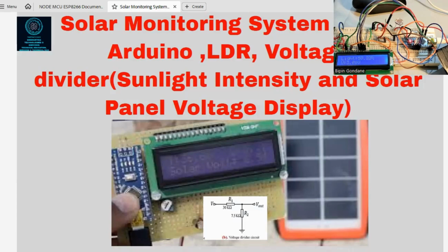What happens is that the sunlight intensity is measured in lux and displayed on the display. You can see on the top it is displayed, as well as the voltage generated by the solar panel, through a voltage sensor, or we can use a simple voltage divider by connecting two resistors, one of 30K and one of 7.5K. So this is the simple project. Let's go to the next slide.